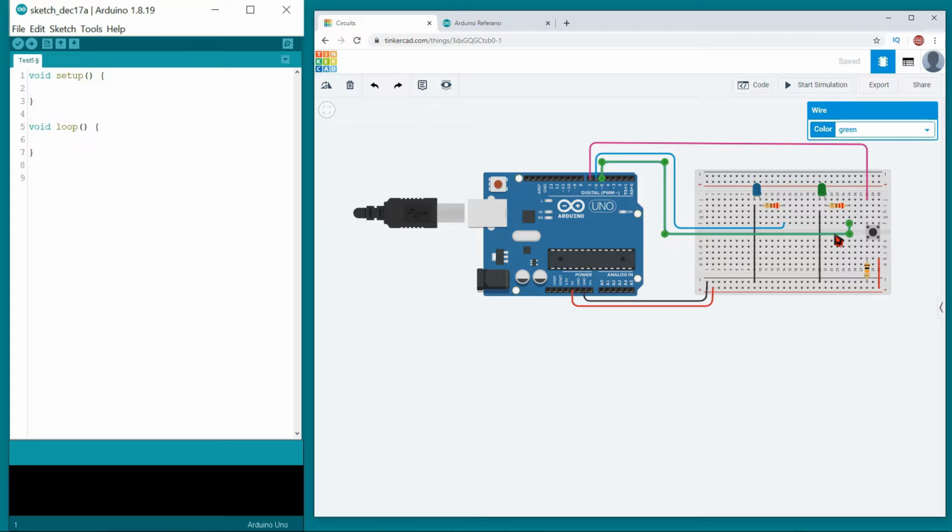The green LED is connected to digital pin 5, as you can observe. Likewise, the blue LED is linked to digital pin 6. But the question remains, should we define these as inputs or outputs? Here, for the LEDs to illuminate, we need to provide a voltage externally from Arduino. Due to the energy moving outward from Arduino, the configuration of output pins 5 and 6 becomes essential. These definitions are made in the setup block.